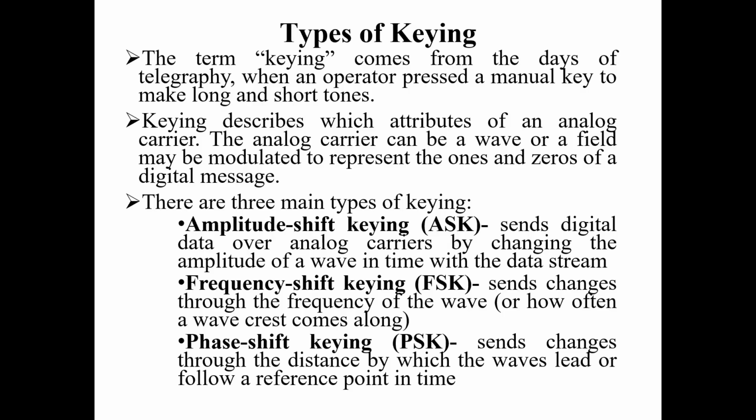Coming to frequency shift keying, the frequency of the carrier wave is changed to represent the bits. Like 1 means one frequency and 0 means another frequency. It's used in some LF animal tags and older RFID systems. It's more noise resistant than amplitude shift keying.